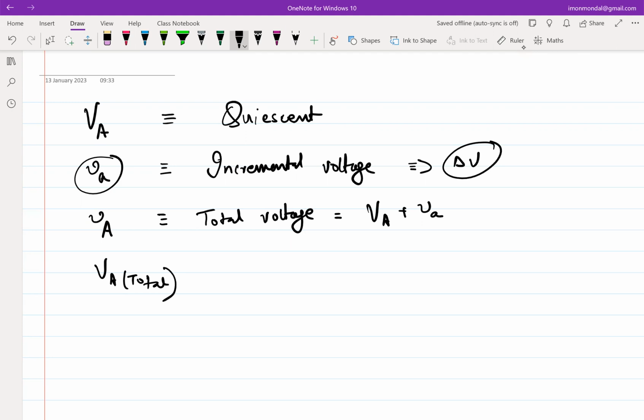That is the direct outcome of the fact that each element is getting replaced by its incremental resistance, del V over del I, or 1 over del I over del V. Which essentially means that in the incremental model, there is no room for anything that is not changing.